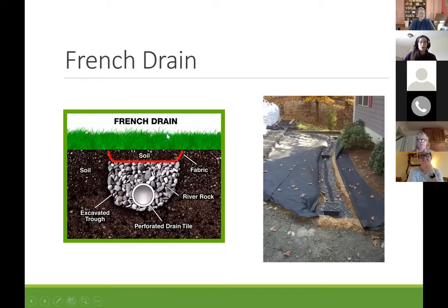So trying to understand the solution. Here, what we're referencing as a French drain is commonly used to capture water from low-lying areas. These are catch basins or boxes with grates on them that are connected to pipes. The pipes in a French drain system are perforated, so we have this rock to try and prevent the movement of soil that could clog up these perforated pipes.